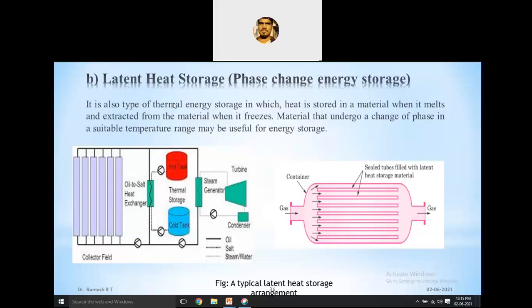They have the capability to freeze without supercooling. Freeze means the phase changes from liquid to solid. Freezing without supercooling, that is what we want. So they have compatible properties, they are conventional materials, and they are easy to construct. Examples are paraffin and fatty acids. They are the two candidate organic substances that qualify as heat of fusion materials.